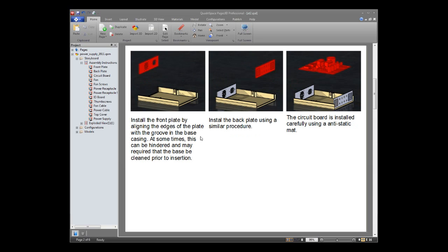And as you can surely guess, we did a very obvious page layout here. We took 3 views and we have big text and everything. There's nothing keeping you from taking and creating your own template. Maybe you want 6 views on a page. Maybe you want a portrait look. Maybe you want a title up there on every page, page number, those kind of things. There's nothing keeping you from setting up the page template however you feel is best for that, and then saving that off as a template of your own. So that's the smart templates and using a template.